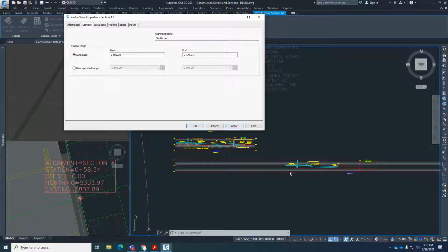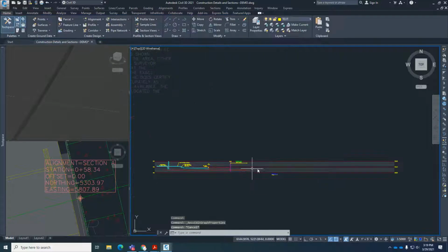I'm not even sure where 0 is at. So I think what I'm going to do is go to a specified user range. And this way it says -1, station 0 somewhere around here. So I guess maybe I'll go with a -50 or something, apply. Okay, should be less than that. So maybe -10 or something. Okay, that's not too bad. I can probably get a little bit closer, -7. I think that will work. And then we've got the same issue with this part of the grid.